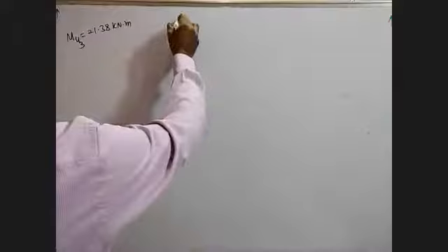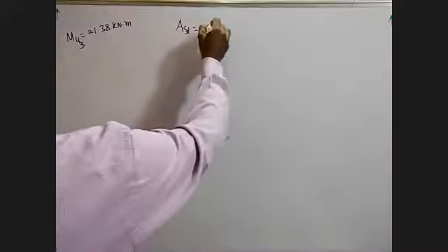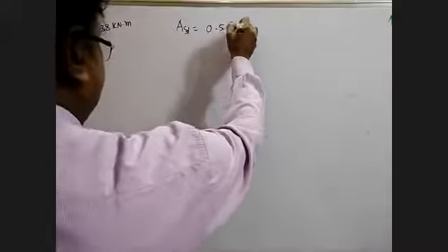So here the negative bending moment is how much it is? 21.38 sir. 21.38 kilonewton meter. Now use the formula AST2, 0.5 FCK.